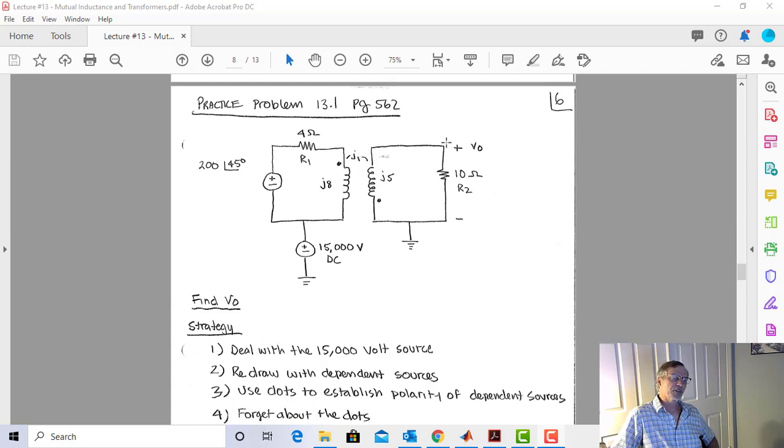Now, let's go to this part of the circuit and measure with our DC voltmeter to ground. Well, the energy transfer for mutual coupling is all based on di/dt, or d phi/dt. But for DC, that derivative is 0. So the DC value is not going to magnetically couple over here. If I measure the DC from here to ground, and here to ground, the DC value is going to be 0. But I am going to take part of this AC voltage and couple it over. So I'll see a remnant of this AC voltage, but I won't see any of the DC voltage. So we say that the transformer has given us DC isolation.